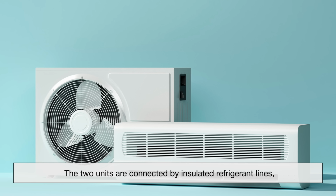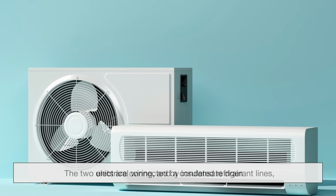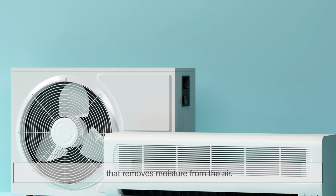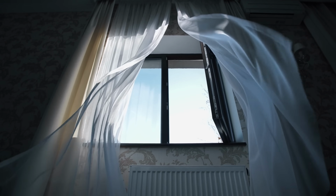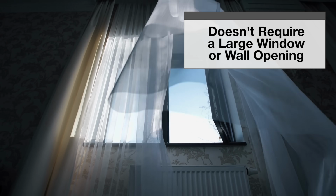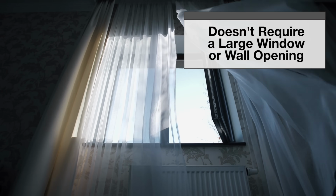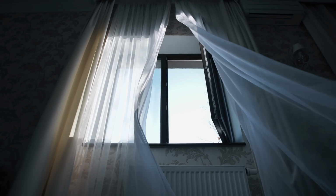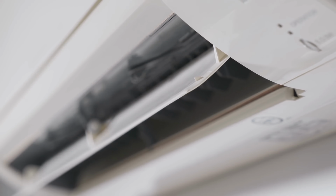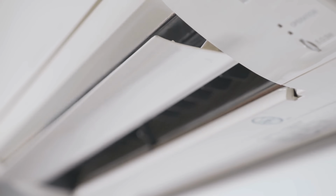The two units are connected by insulated refrigerant lines, electrical wiring, and a condensate drain that removes moisture from the air. Because the system is split, it does not require a large window or wall opening like traditional window air conditioners, which makes installation more flexible and allows for a cleaner, more discreet look inside the room. This separation of components is also what allows the indoor space to remain quiet, as the noisiest parts of the system, the compressor and the condenser fan, are located outside.